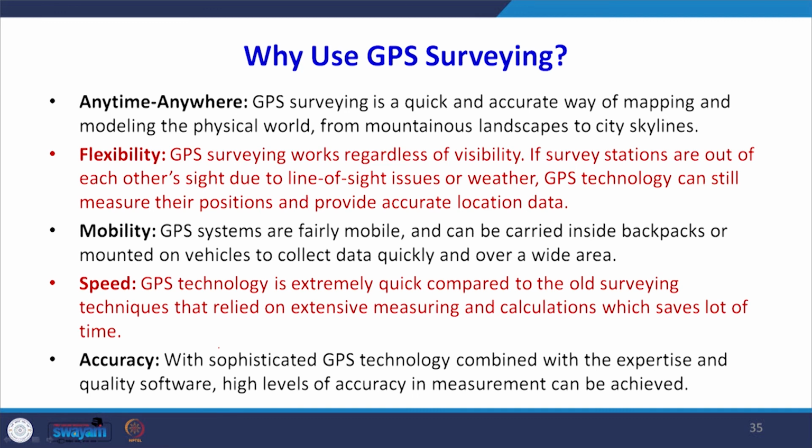Accuracy level, I have shown you the different methods. If we are selecting the right kind of GPS unit, and using the right kind of method for a particular application, we can get very good accuracy from these GPS devices. We have to post process the data, of course. So, we require some knowledge of how to post process the data through software in order to get good accuracy. So, this is all about this lecture. Thank you very much.